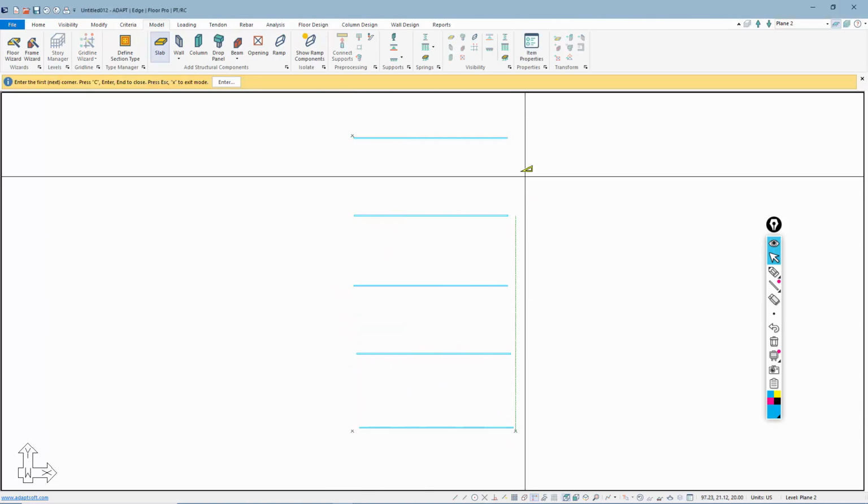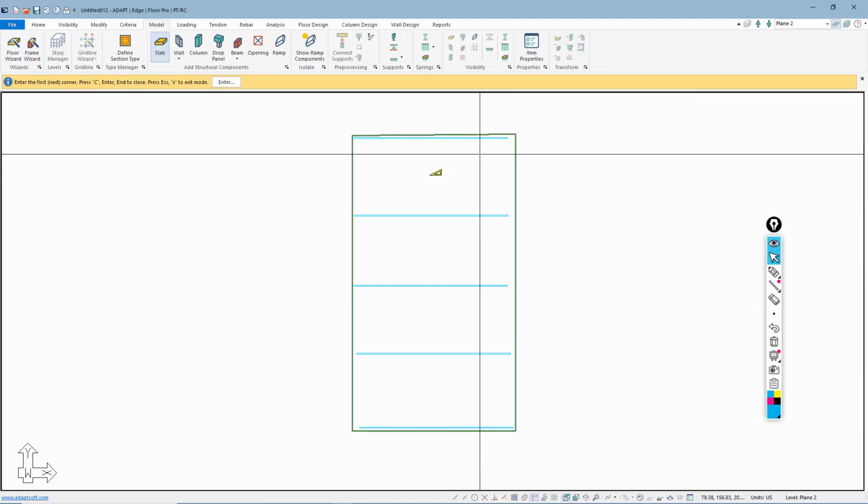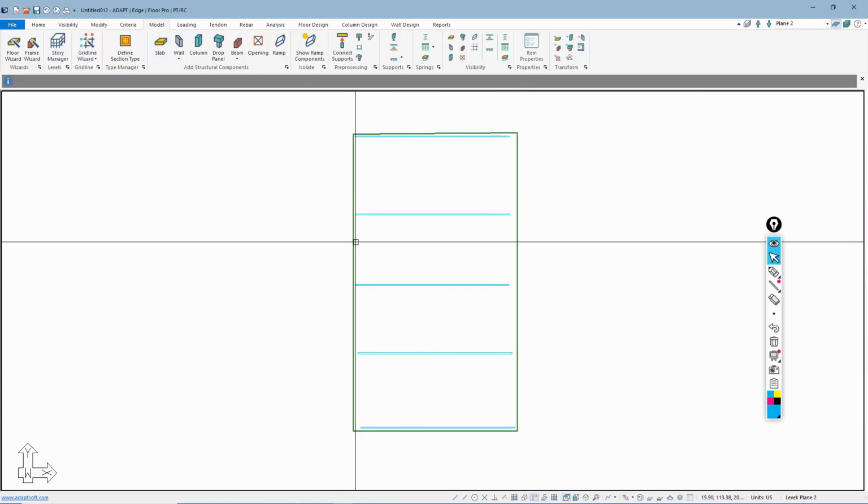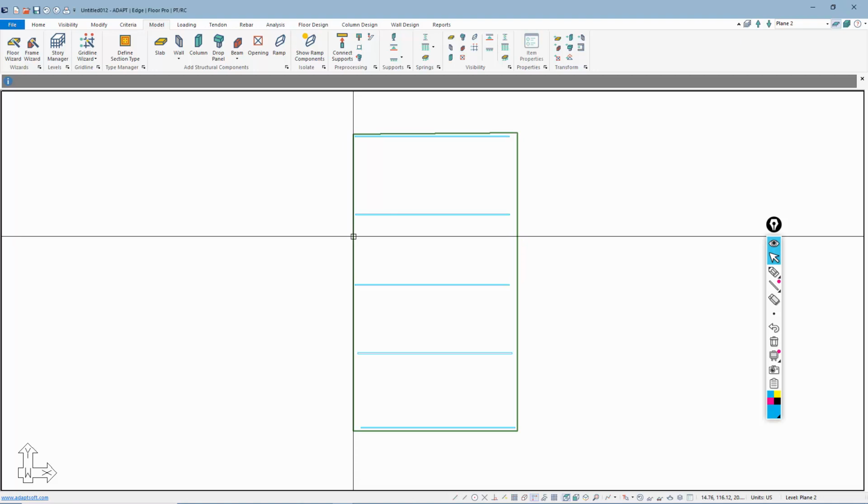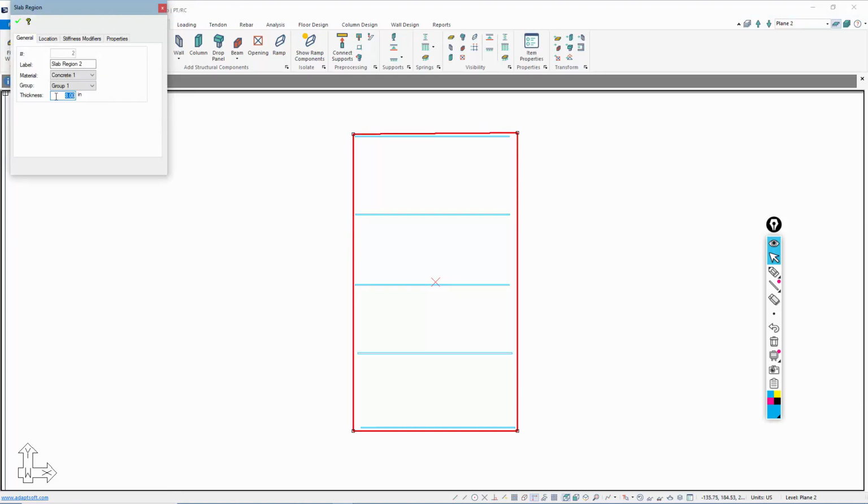Again, if we had a reference file, a DWG, this would be more exact. This is just adding something onto the structure. Similar to walls, I have two options here. I can equate this thickness of the slab using the defined self-weight of this property, concrete 1. This equivalent thickness might be 2 or 3 inches.